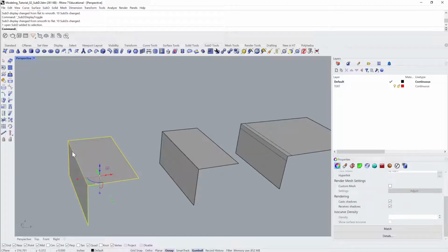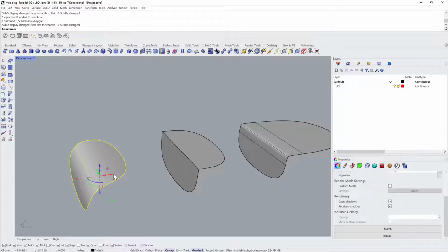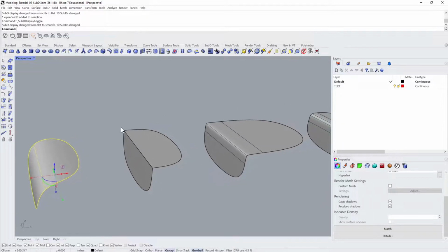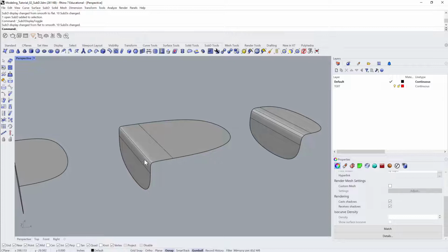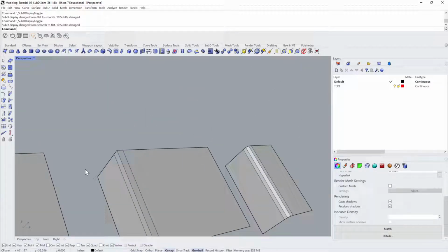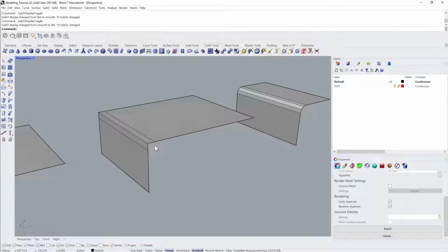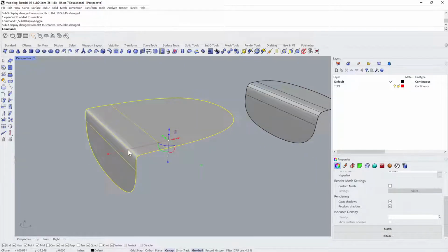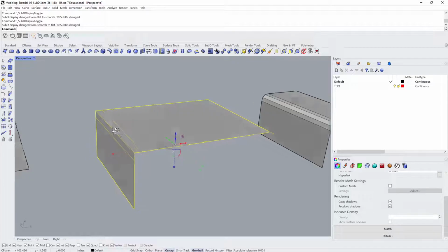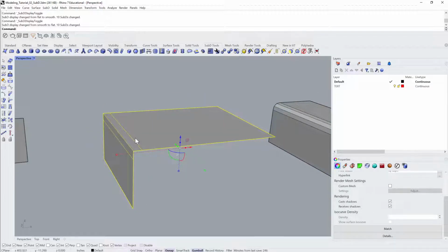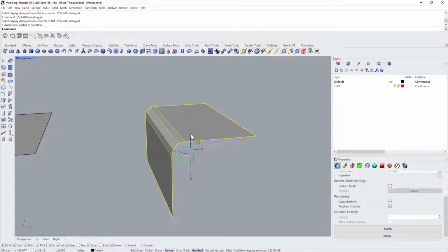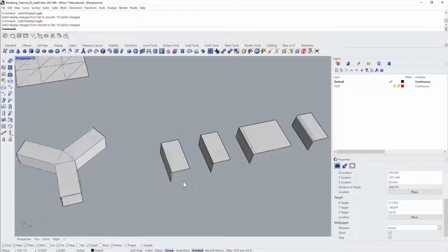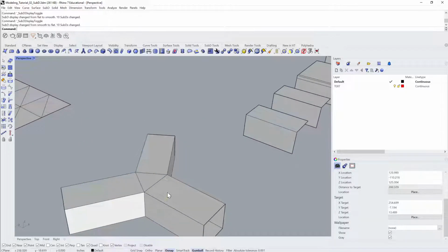All right, so we have 4 different ways of turning the corner. We just have one poly edge here, and that gives us the most gradual radius. We have the crease, which gives us a really sharp turn, or like a 90-degree bend in this case. We can use these offset edges using InsertEdge and tighten the way, create basically a weight around that edge. And we can vary the distance of these things to control the transition, or we can use the Bevel command to insert that.